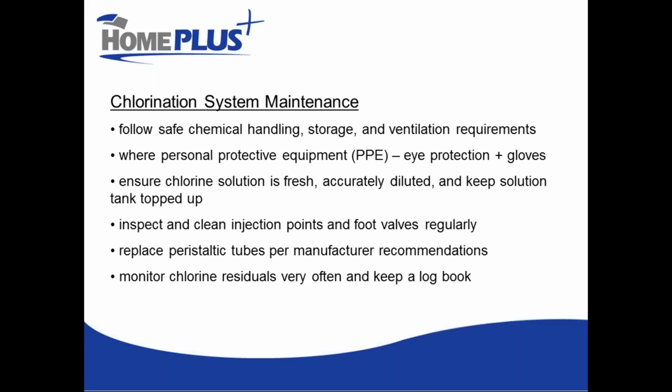They're probably the most common point of failure, and they're easily cleaned and inspected or even replaced. They're not very expensive. In the peristaltic metering pumps, replace the peristaltic tubes regularly. Keep spare ones on hand for sure. And of course, monitor your chlorine residuals and keep a logbook that you can refer back to.